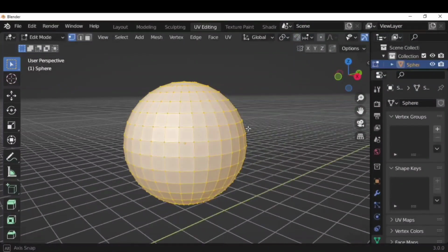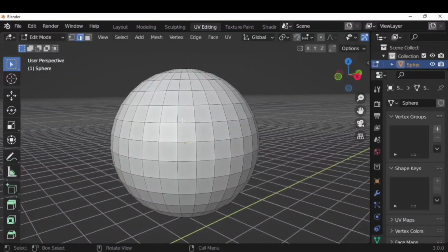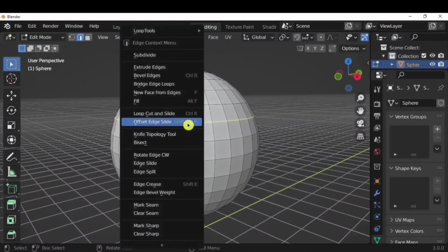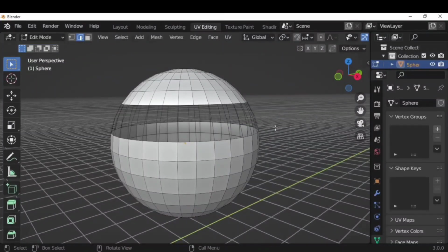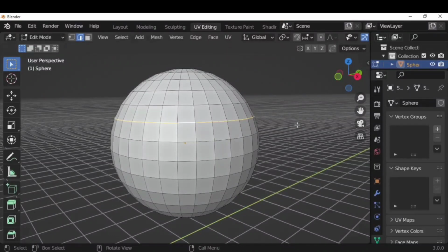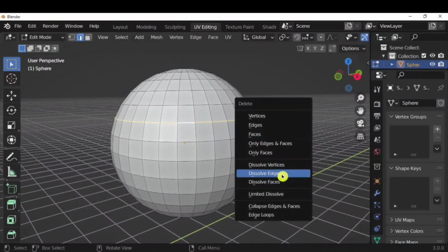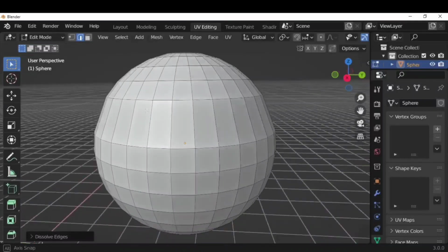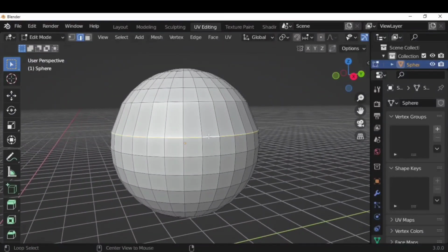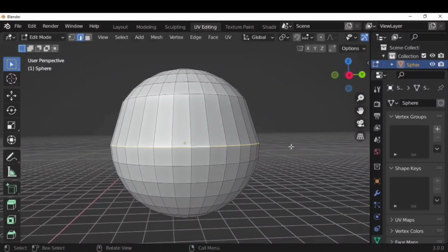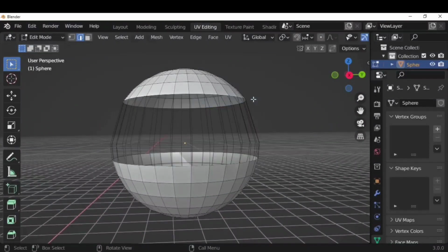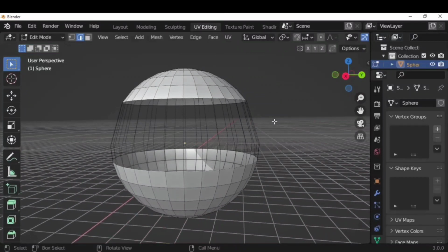Let's use deleting and dissolving edges to your advantage. So right now, let's say I'm selecting this edge, and if I press X and delete the edge, you can see that there will be a void like this. But if you dissolve it, there is an option of dissolve. If you come down, now you can see the edge has gone but the planes are still here. Now let's do it again, and this is something that you have to decide, whether you delete it or dissolve it, will give certain results to your project.